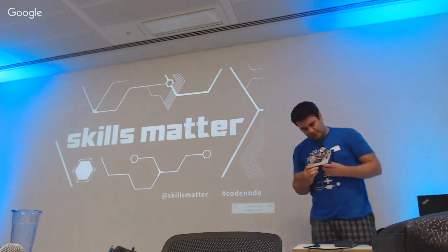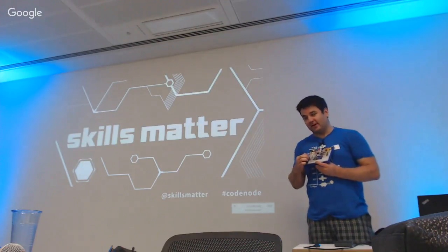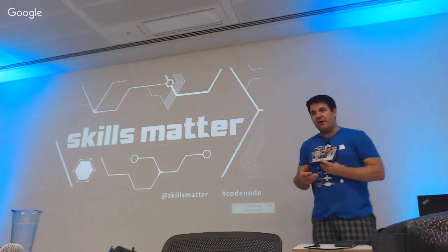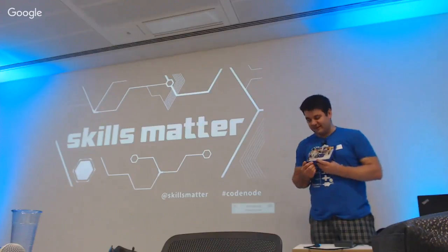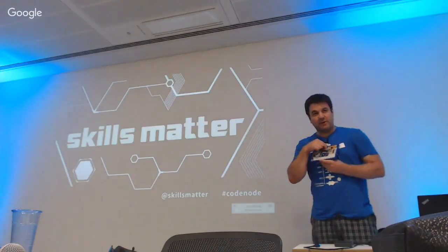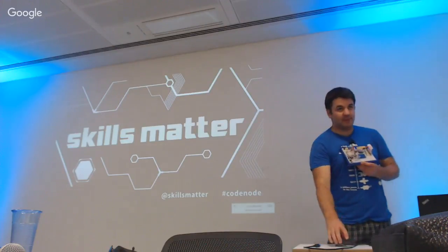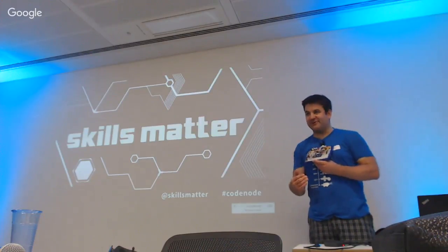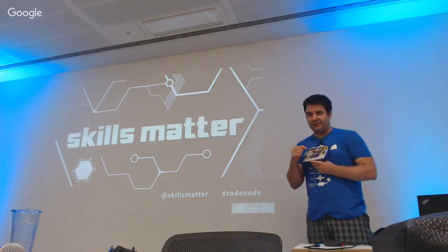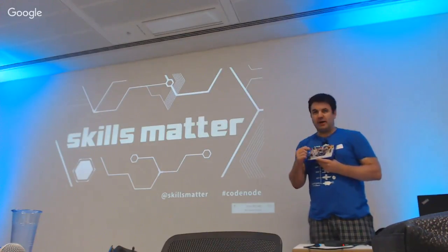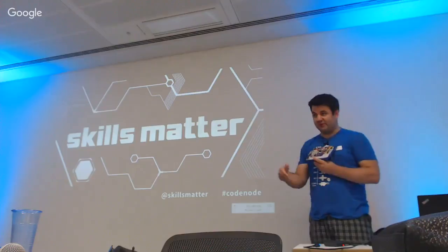So the basic tech here is I've got PIC BASIC, which is a compiler that compiles down to an assembler file that can then be programmed into this. This I've actually programmed with MicroPython, because I'm running the main game in Python on the Pi, so I wanted to keep the number of languages down to as few as possible. This actually has a little facility where it can self-update. So it can download updated MicroPython firmware from the Raspberry Pi as I publish new versions.